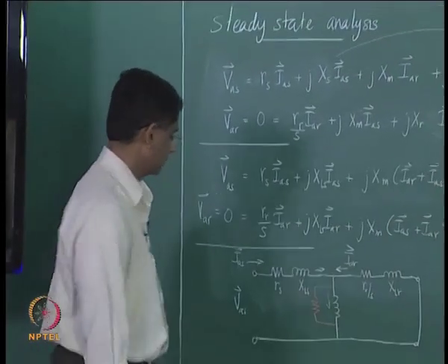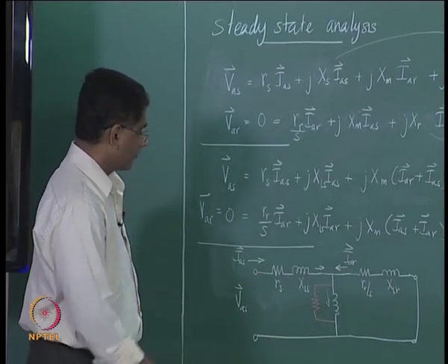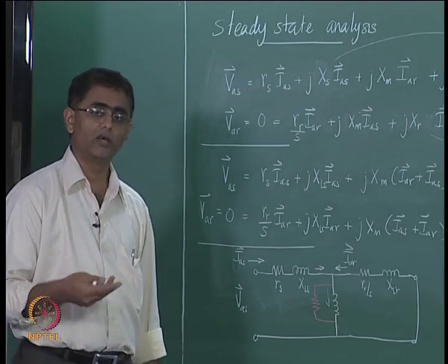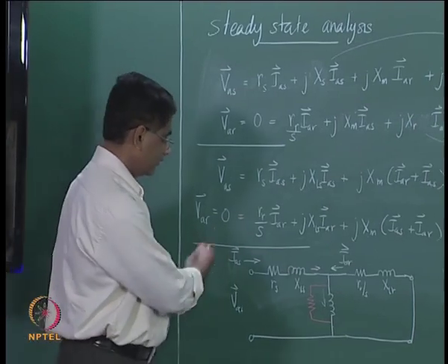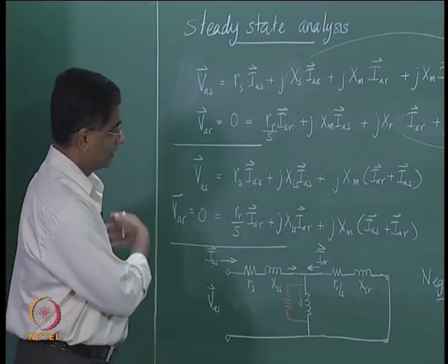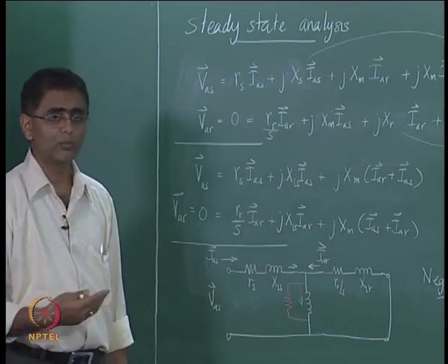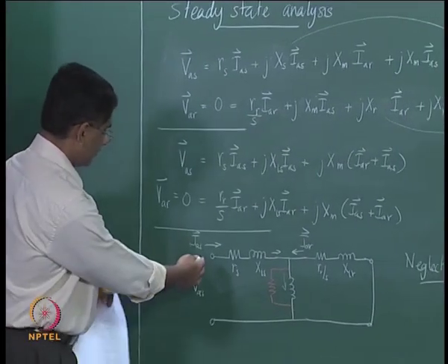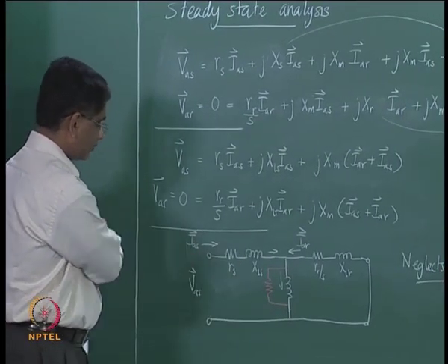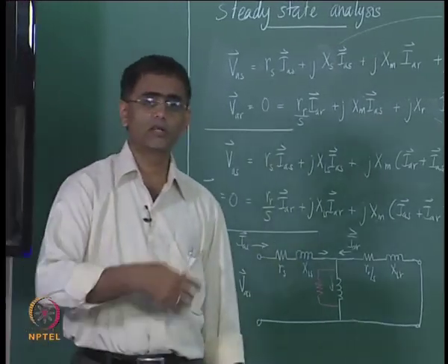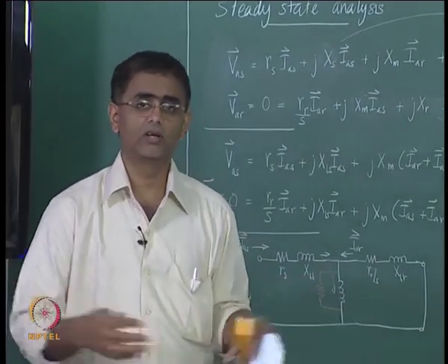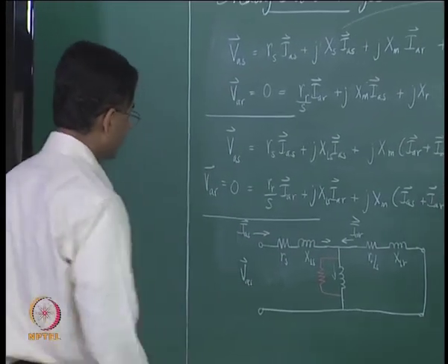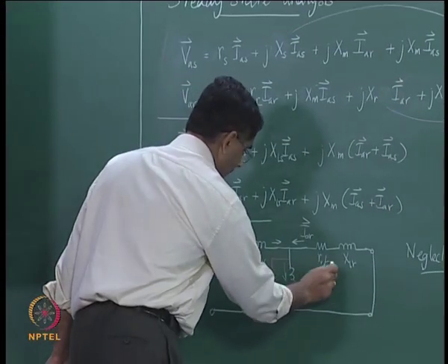in the first course on machine. So, from this then one can go about to predict all the machine behavior under steady state, one can derive the speed torque relationships and then the various approaches to speed control one might have, and then if you are going to connect this induction machine to a big electrical network, one can solve it as an equivalent electrical network to find out how the machine is going to behave at a particular slip.